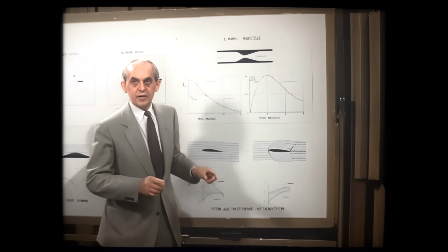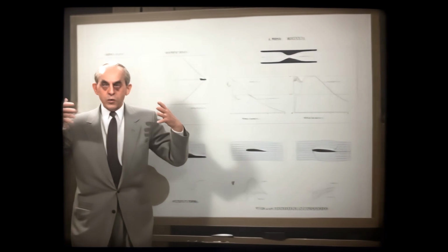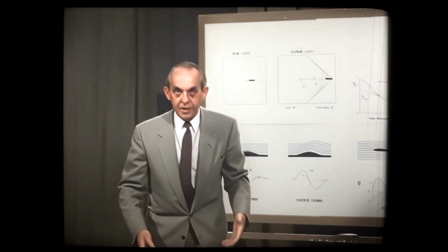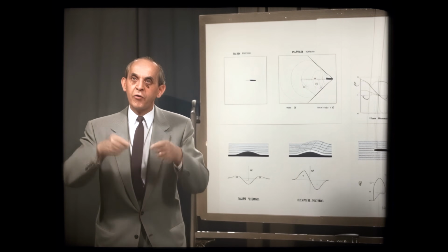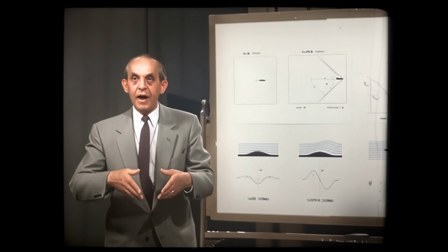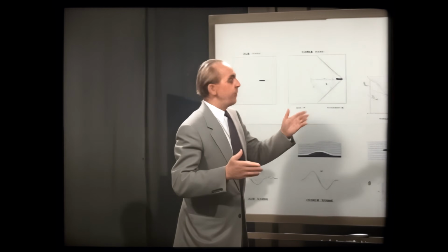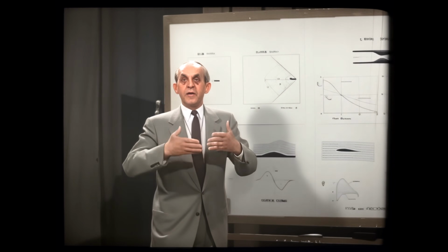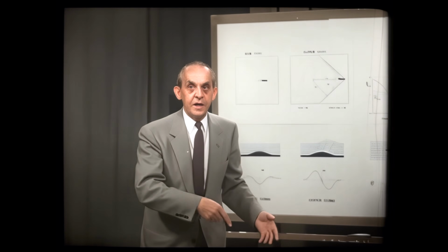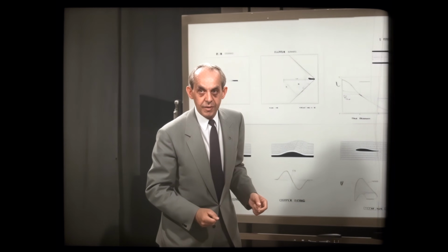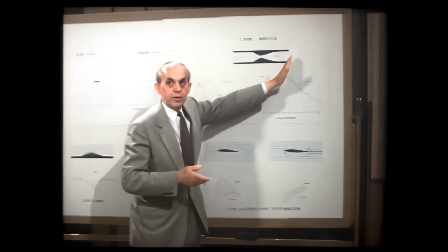This is necessary because due to this increase in speed and decrease in pressure, the density of the air gets lower and lower, and therefore beyond the speed of sound, the density decreases more than the speed increases, and we have to open up.